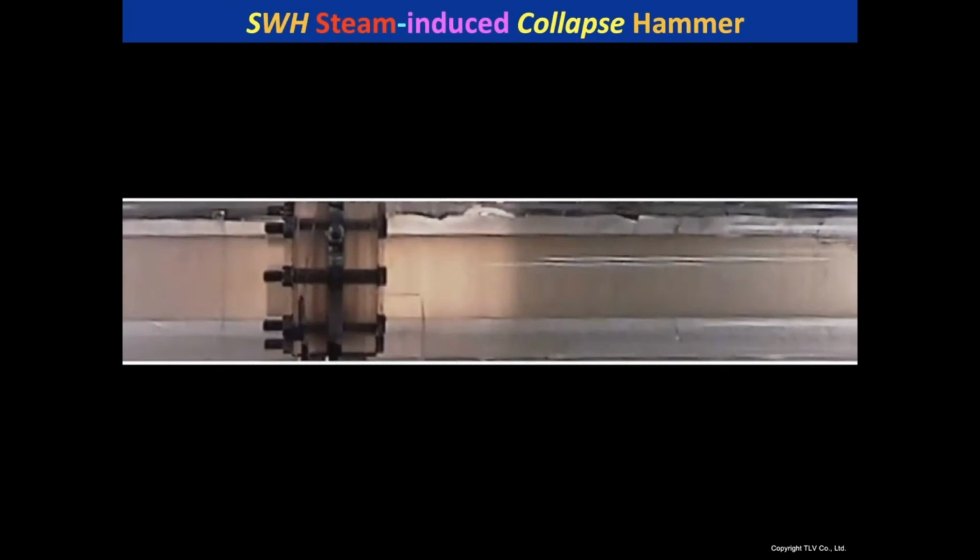So if you recall from the prior presentation, this is a video shot of acrylic piping solidly filled with condensate. It's in TLV's R&D lab in Japan, and the pressure is around 7 or 8 psi. When you take hot condensate through a steam trap, it's going to have flash steam because it's coming from a high pressure to a low pressure, and that flash steam creates a pocket, and those pockets can collapse. Watch how quickly those pockets can dissipate and collapse, creating collapse hammer where the shock wave is directed to the pipe wall. Here we go.